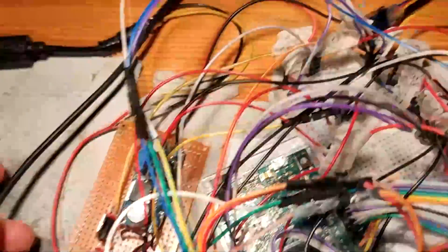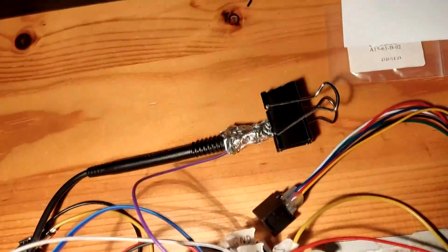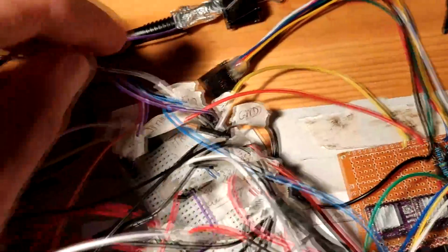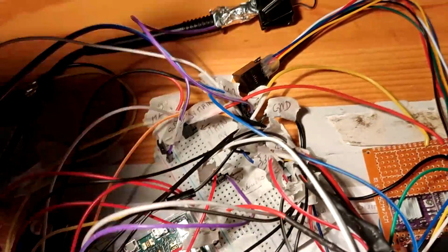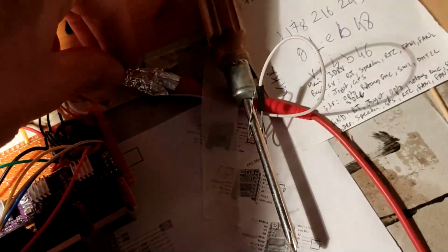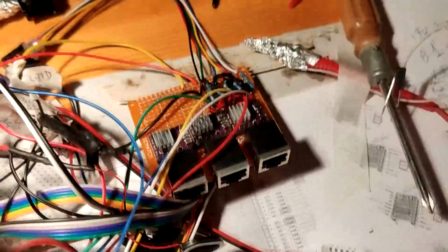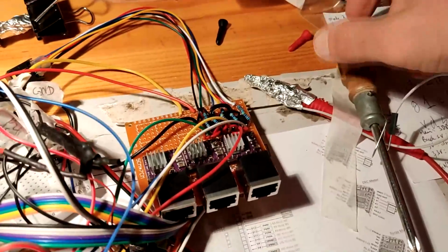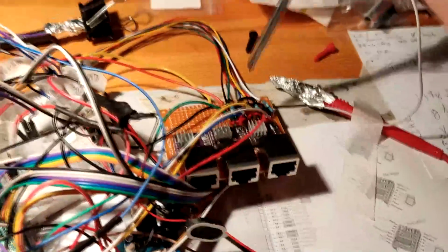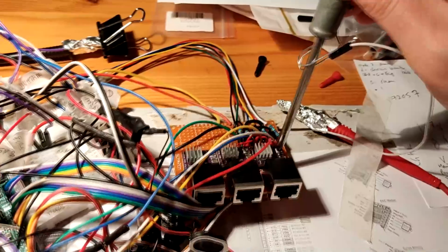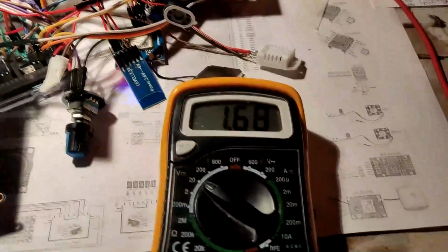So I have here a voltmeter and the black wire is on the ground of the circuit and the red wire is connected to a screwdriver. We have to adjust the voltage reference of these drivers to half of the max amperage by coil using this screwdriver. So we carefully put the screwdriver on a little screw on each driver.